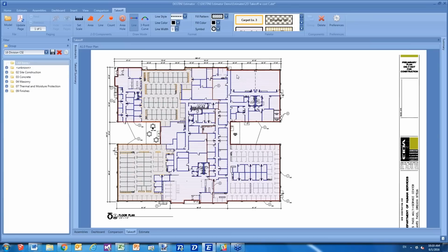First and foremost, you can see that I have some quantity takeoff already done here in my takeoff view. When you add any costs or quantity takeoff, whether that be 2D or 3D, the filter view, which is this view to the left, will filter on both of those things, so both costs and your 2D and 3D quantity takeoff. And this is really handy because when I sketched these different lines and areas, all I told it was its draw style.